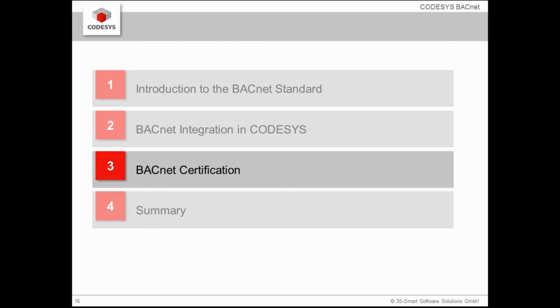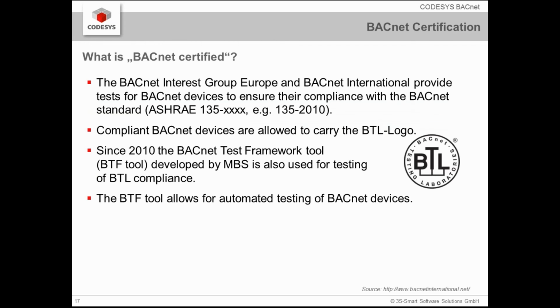So let's have a look at BACnet certification. At first, what does BACnet certified mean? The BACnet Interest Group Europe and BACnet International provide tests for BACnet devices to ensure their compliance with the BACnet standard, for example, the ASHRAE standard 135-2010.